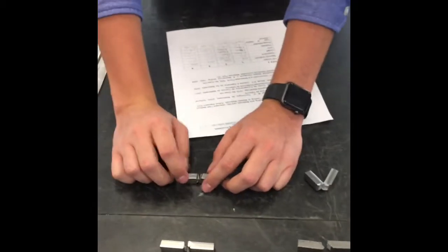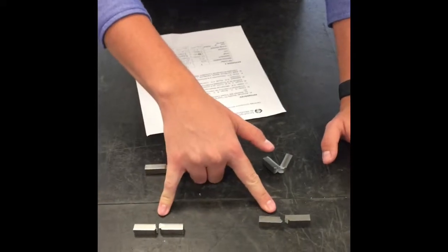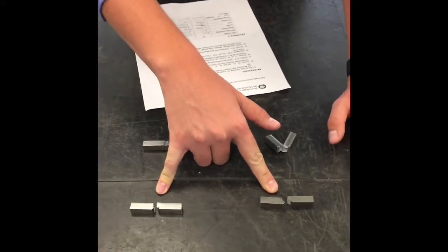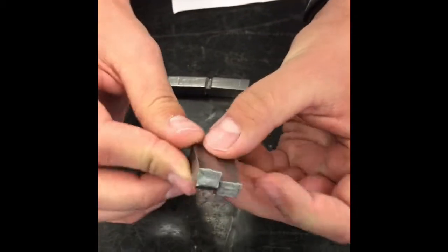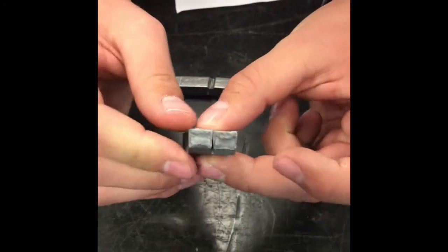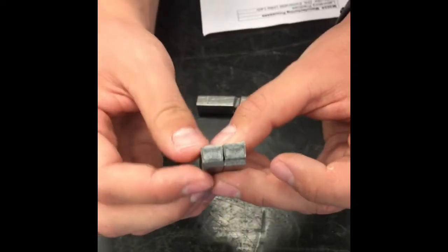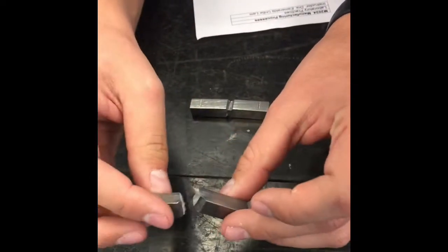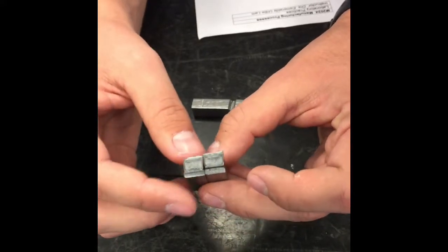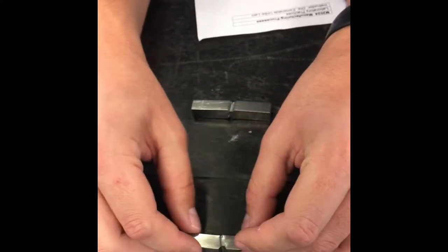And when we tested in the cold temperatures, we have to do it really quickly because the temperature could change easily. These two materials were in minus 15 degrees Celsius inside the fridge, and as we can see right here, the type of fracture is brittle. So as a result, we can see that in a difference of temperature, especially when it's really cold or colder than these ones, we can present a brittle fracture due to the temperature, as I said.